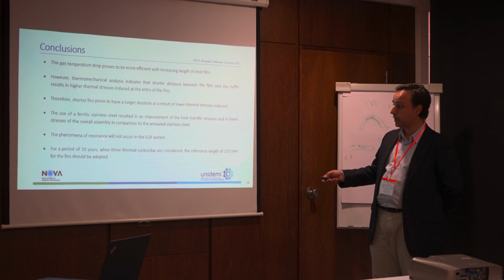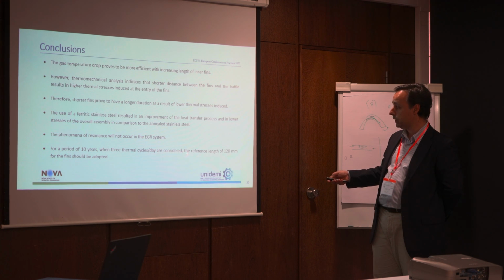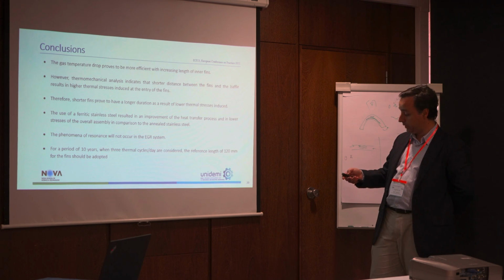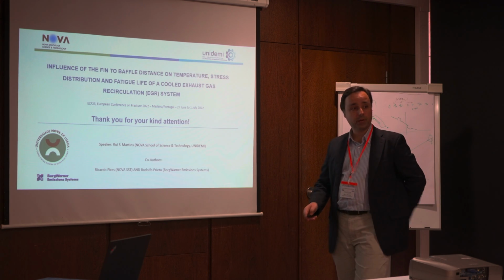The phenomena of resonance will not occur in the EGR system, and for a period of 10 years, when 3 thermal cycles per day are considered, the reference length of 120 millimeters for the fin should be adopted. Thank you very much for your kind attention.